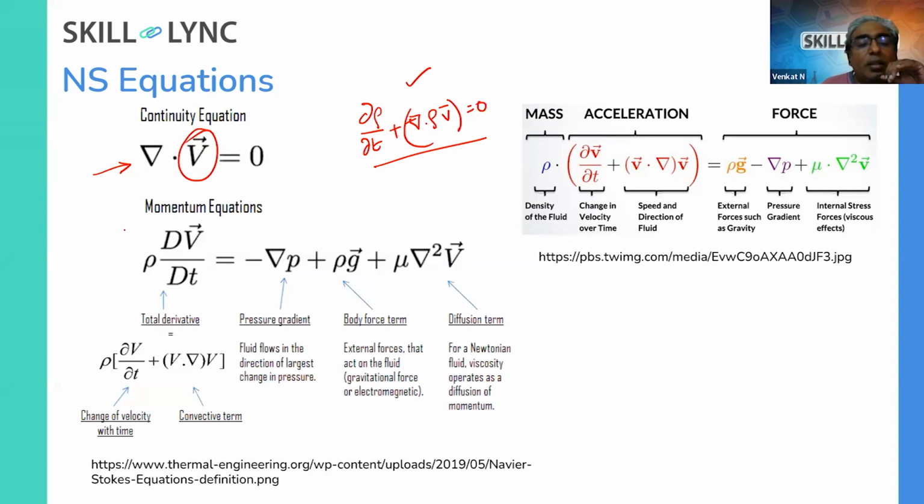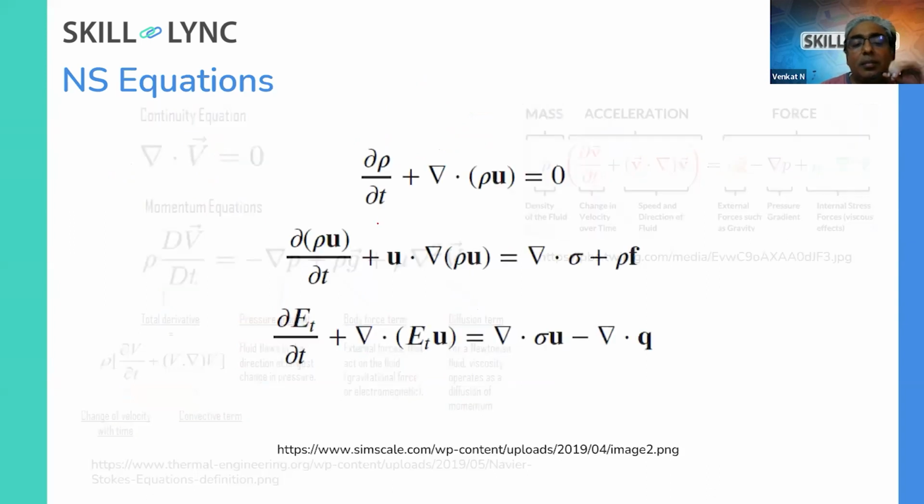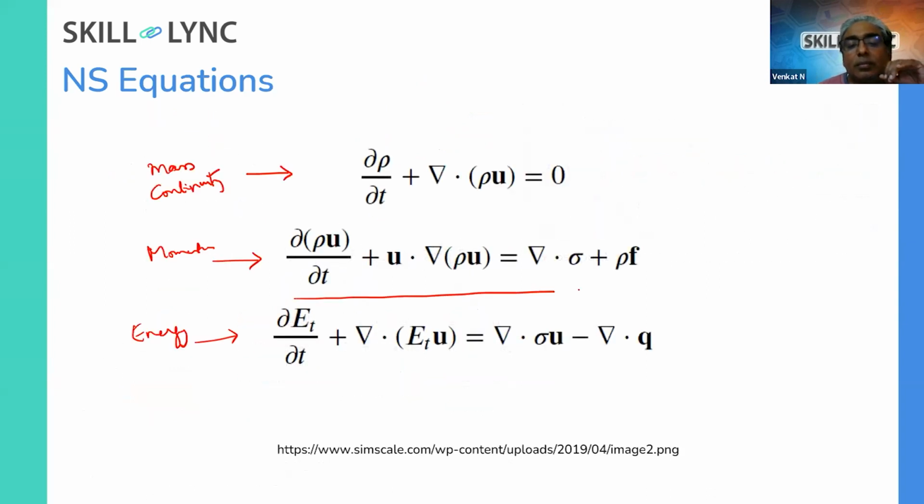Now, this is the momentum equation. If you see this, ∂(ρu)/∂t plus u dot ∇(ρu) is equal to the shear stresses and the body forces.